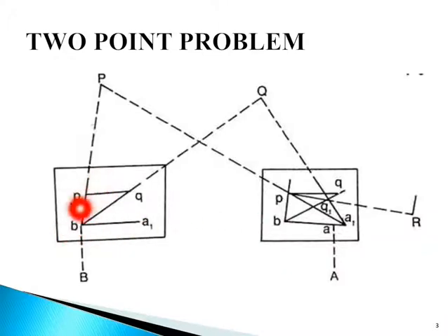We have already drawn the rays from station B to connect these two points, and the point where they intersect we term as small b. With the alidade touching b, the ranging rod at A is bisected and a ray is drawn. Then by eye estimation, a point A1 is marked on this ray. So the table is shifted and centered on A.